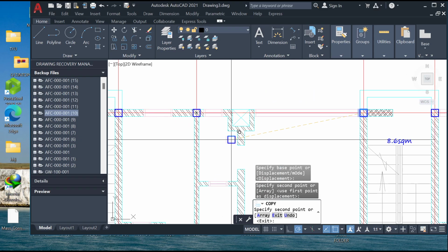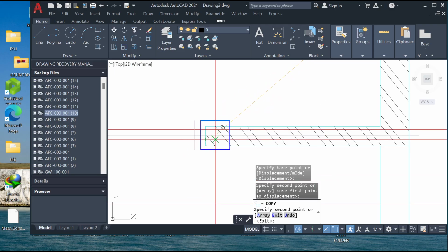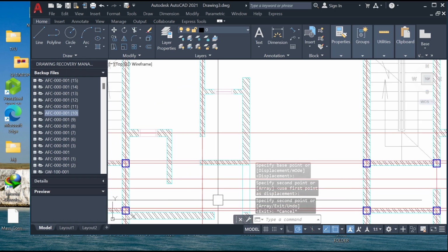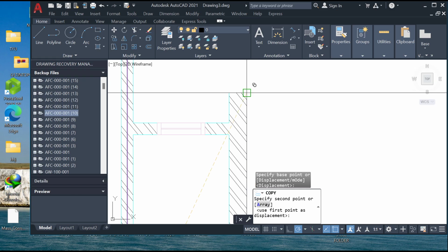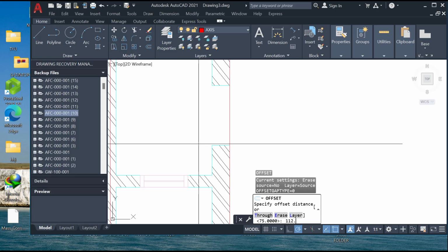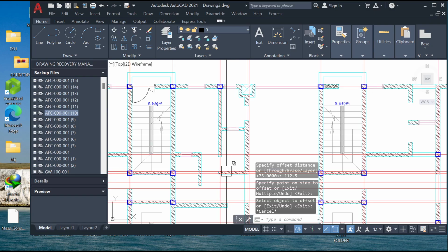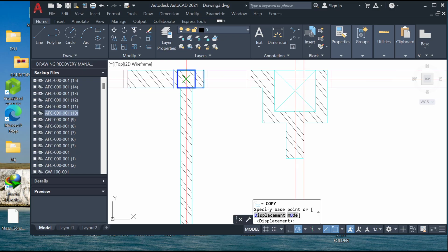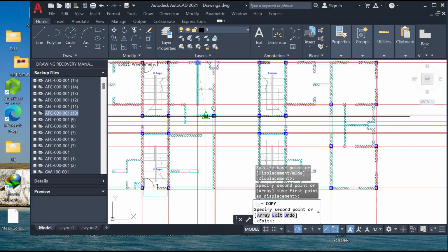Very good. Okay, so if we put a column here, it's actually protruding outside the door. So let's have a grid line here. Yes, let's have a grid line here. So we have 0, enter. Then we have 112.5, enter. Very good. So you can see that the GA, which is the general arrangement, is actually coming out very fine and very neat. Then let's have a column here too.